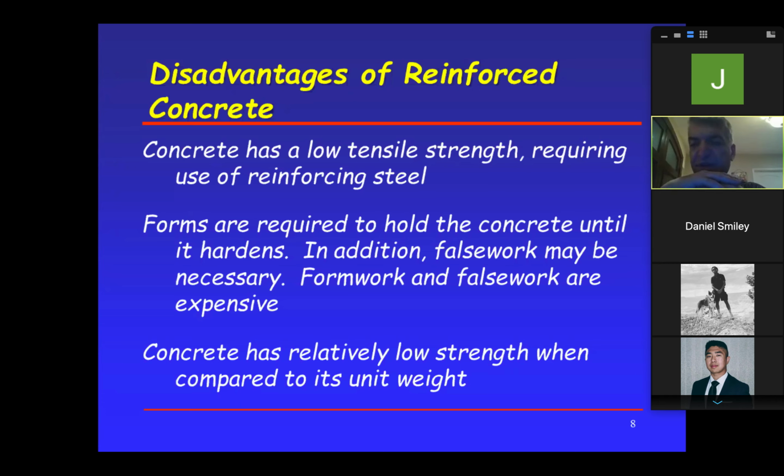When you drive on the freeway and you notice a bridge being built, you will see the forms that they shape the bridge with to pour the concrete in. But underneath that, you will see so much wood going right, left, up and down, and all that stuff. That's the false work. The false work is mainly there to support the forms so that it doesn't fall down.